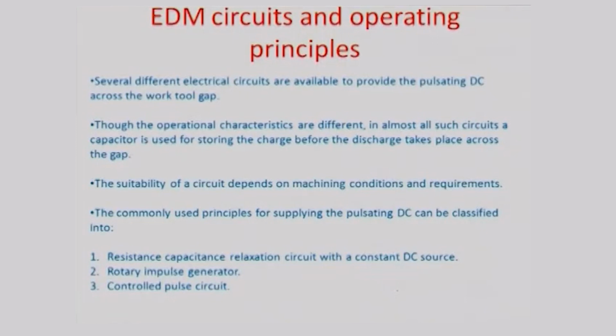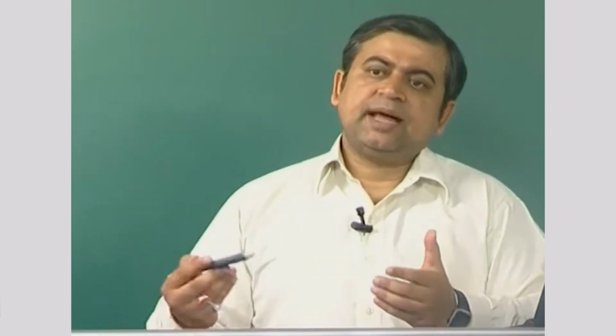Now, we will come to a very different aspect of the problem. We are talking about a case where we have to keep on feeding voltage in sparks, and somehow the frequency at which energy is being applied should also be optimized with the frequency at which the spark is formulated. Otherwise, typically we are losing energy if we give a continuous supply of energy and let the process follow by itself. So, the point of time when the spark is formulated should match with the frequency at which the energy is being supplied. So, the packet comes and it gets delivered, and then there is another packet which gets delivered.